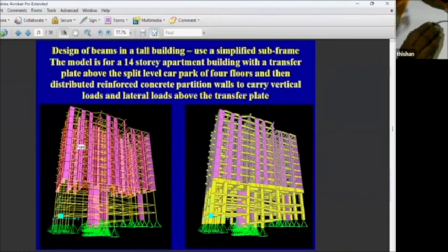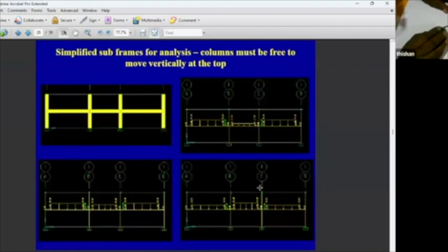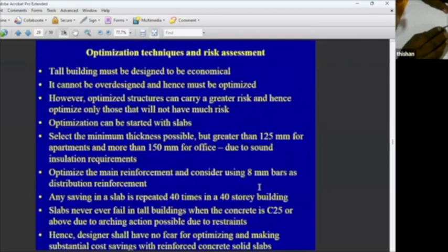At this particular level, you can see there's a transfer floor. It consists of transfer beams and a top slab. If you look at the right-hand side diagram, it's clearer. Here you can see big beams when you compare with the other members. These beams are 1.5 meters deep, generally of square section, close to square, not rectangular. And we will see why it is important.